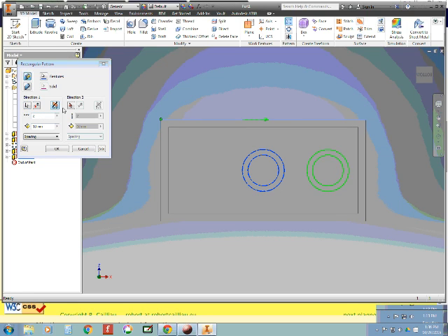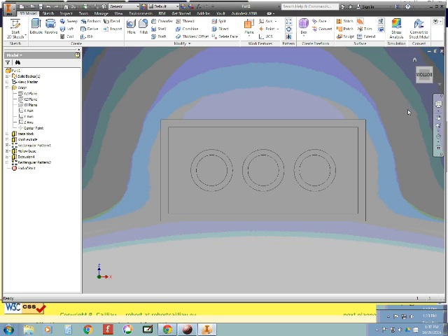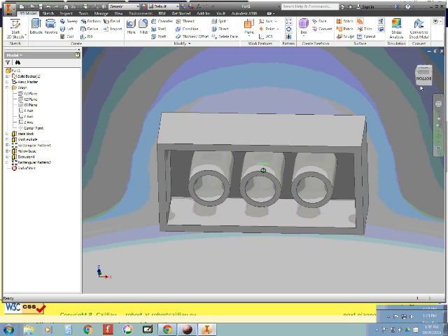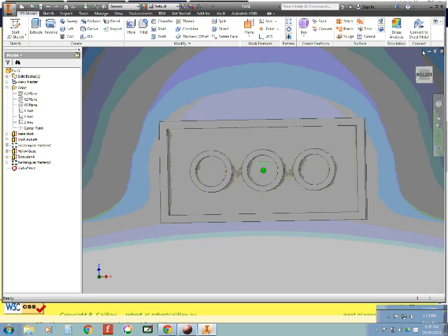And now we can pick the fact that we want this to be the middle. So we pick the direction, we tell it we want this to be the mid plane. That means we're going to go 2 directions, and we want 3 of these. But the distance between them we want to be 8 millimeters. And leave it on spacing. That means the distance between the objects. And then click on OK. And have all those. Pretty simple.